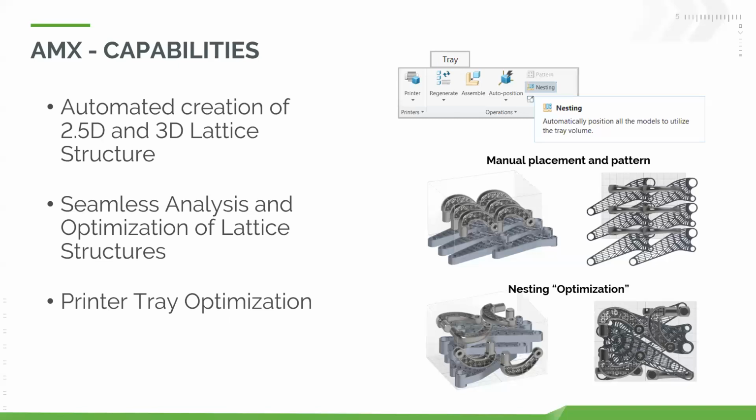One thing that you also get as part of the standard additive manufacturing extension is a 3MF file. This is a big upgrade from what you would typically think of whenever you're working in 3D printing, where normally you'd just be using an STL. You get access now to a 3MF file that allows you to include much more into that file itself. You can include different types of material settings, different types of orientations, or even different types of appearance settings in there as well. So everything that you'd want to send out ultimately to the printer, you can have that included in that 3MF file itself.